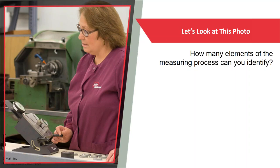So take a look at this picture here. This is a typical measuring process that's happening in a shop environment. How many elements of the measuring process can you identify? Let's see what we can find. The first one down at the bottom is the standard or the master. This could be a master ring, a master disc, a gauge block, some reference standard. The second part of the measuring process is the workpiece, the piece that we're actually trying to measure and find the dimension of.